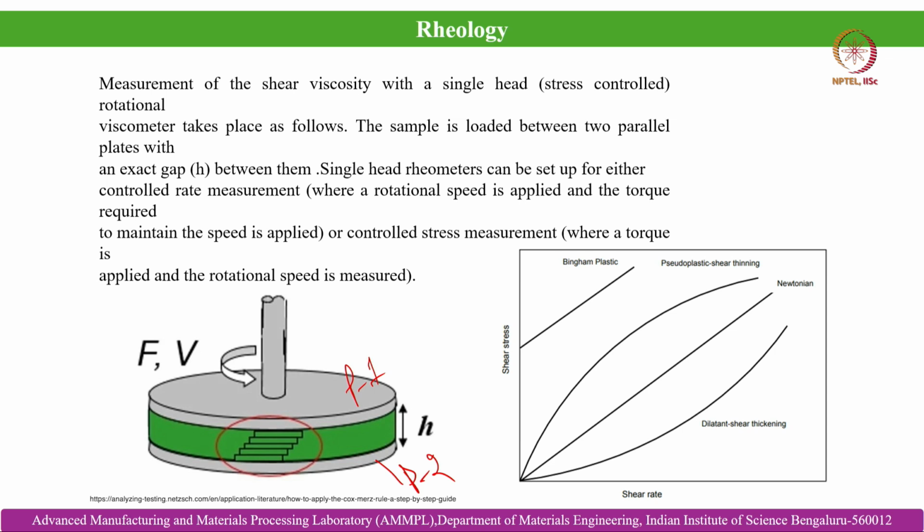As you recall, I discussed in the earlier class that rotational viscometers can be defined as Searle type and Couette type, in the case of cup and bob geometry, but the viscometers can also be parallel plate type, where it can be rotational and also reciprocating. So there are several variants of them, but the end goal is basically the same: to evaluate the viscous evolution of the solidifying slurry. We are talking about liquid melt here because that is our subject of consideration.